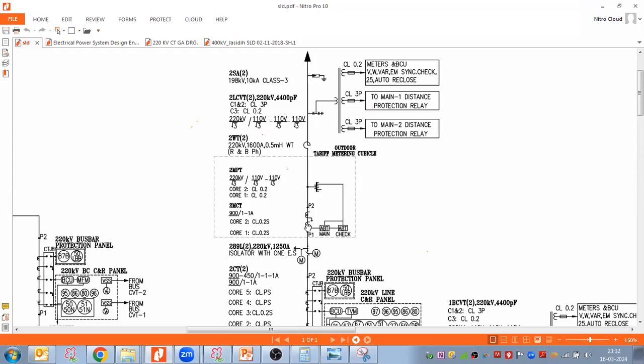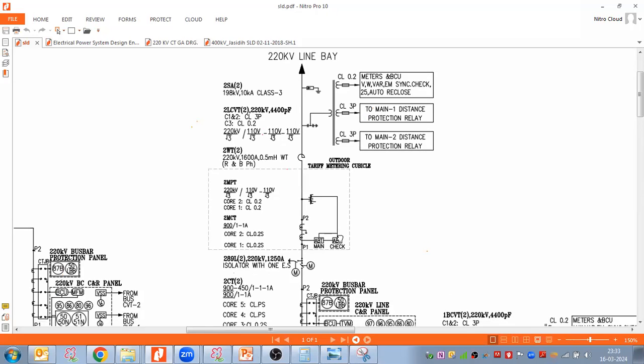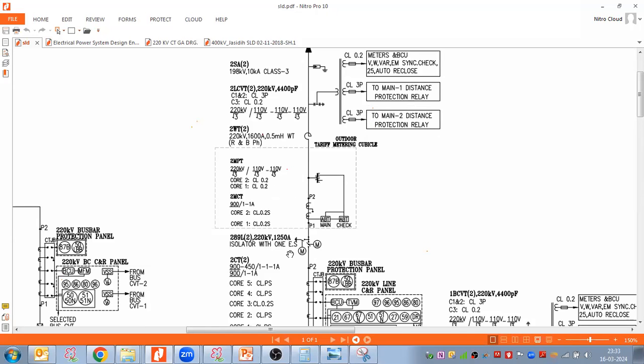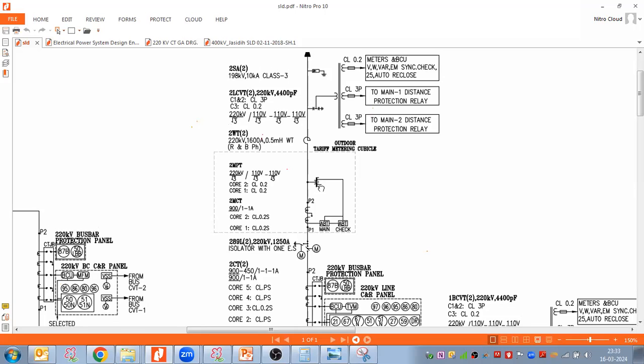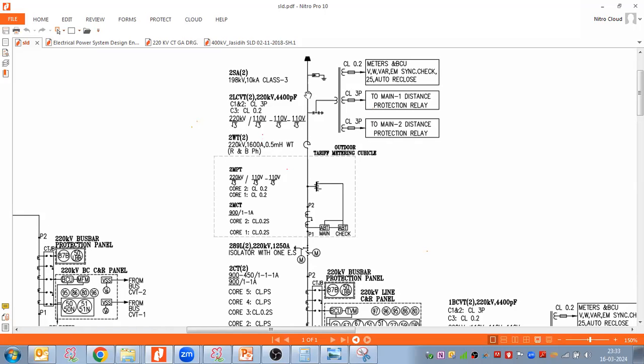So one thing in that: we are measuring the current first, in metering. CT first, VT then. Otherwise we are losing the losses inside the PT. Yes, because this is the exporting line. Correct, CT first, this is the exporting line.